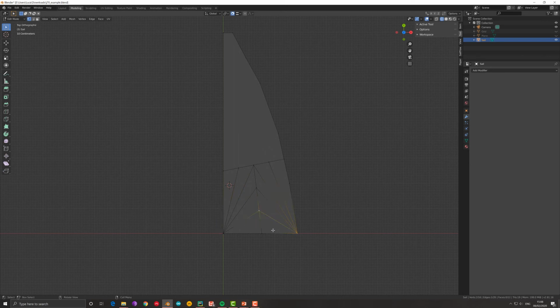Okay, now I have created the lower part of the sail. Let's go to the crosscut on the top, which I have to do manually. So with the knife tool, I click on one side, I click on the other side, I press enter, and I have the cut. I do that also for the other bit. K to go to knife mode. In this case actually I subdivided to make it easier to find the middle of it.